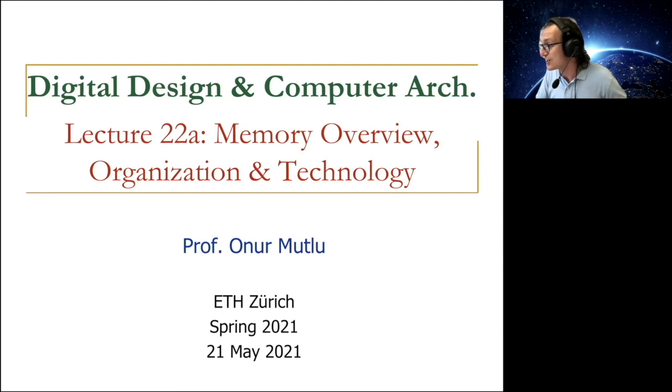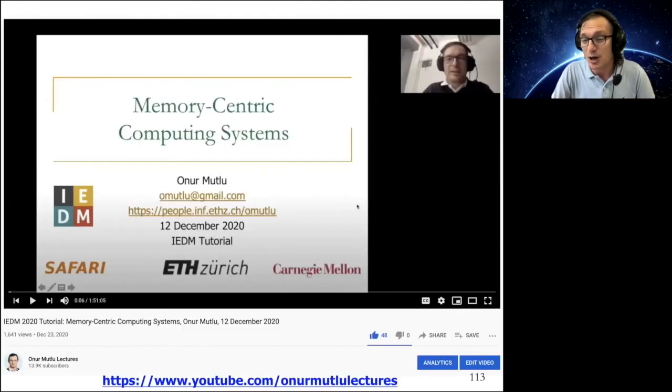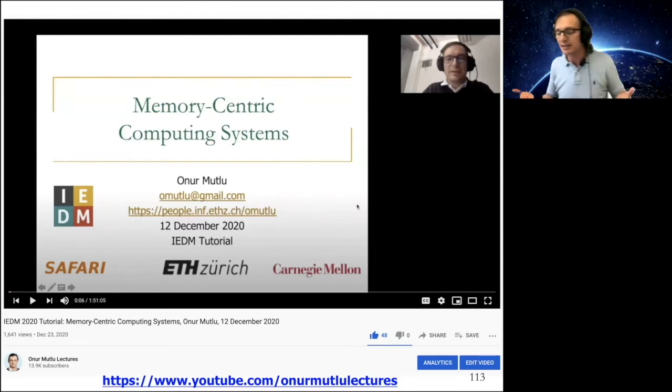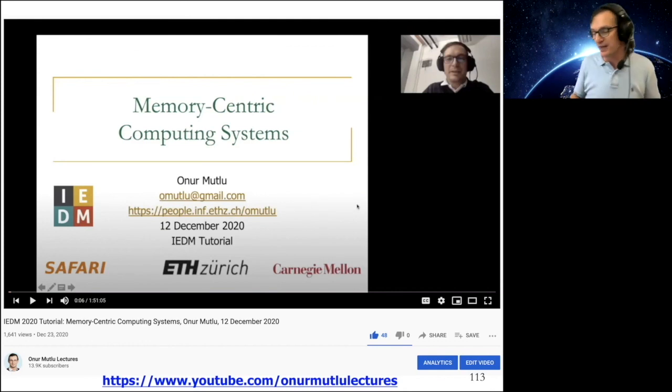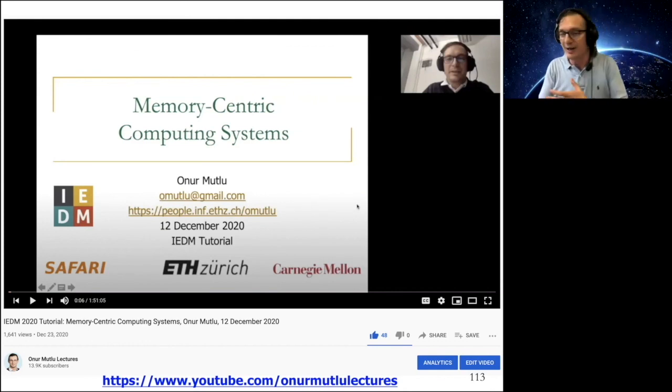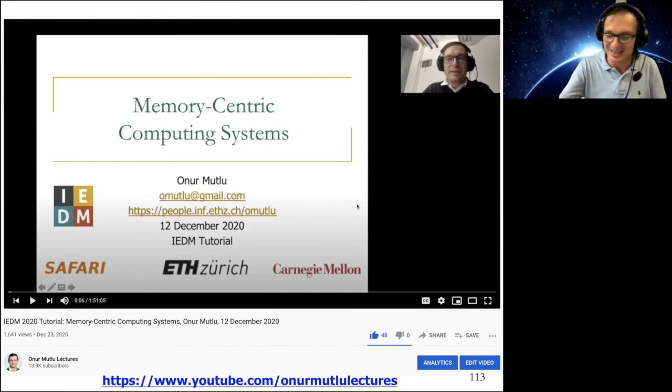There's one more question. Is it also vulnerable to some kind of RowHammer attack? That's another excellent question. I believe internally, yes. RowHammer is an example of a read disturbance error. What does disturbance mean? Whenever you access some memory cells, you disturb some other memory cells. This phenomenon is very fundamental. It happens in hard disks, but hard disks have a lot of error correcting codes, so they correct many of these errors before they supply data to you.